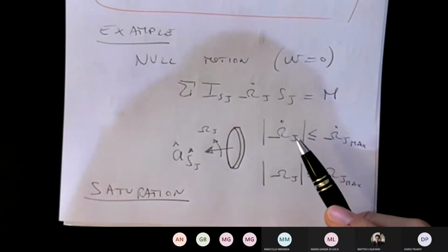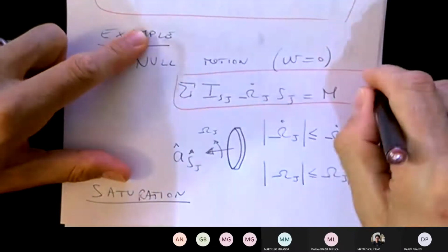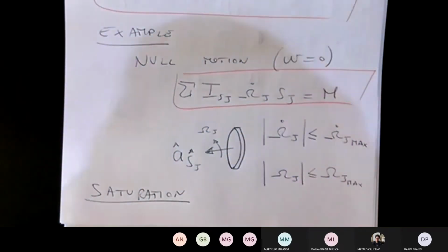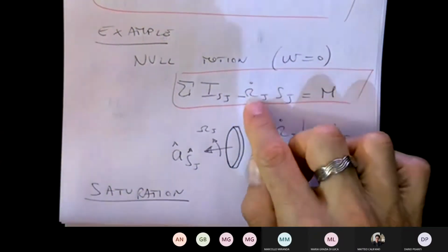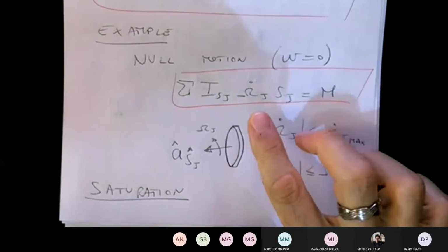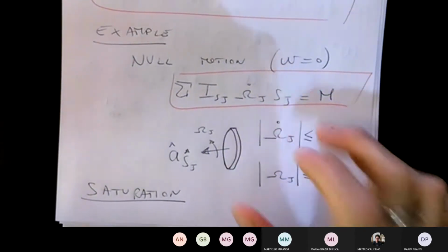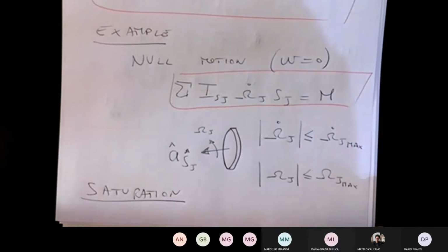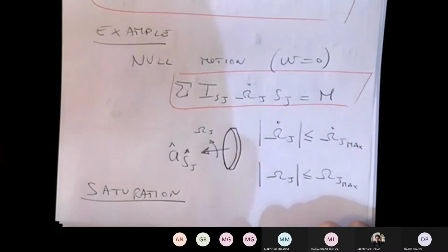So what is usually done is exactly what's described in this equation here. Say that your spacecraft, you don't want to perturb the motion of your spacecraft, maybe it's at zero angular velocity, but you need to slow down the wheel, so you have to actually apply some non-zero omega j dot. Well, what is done is that you desaturate, so you start slowing down, for example, that wheel, but you need to compensate for the torque that it's creating. And so that's done with thrusters or maybe with your magnetic torquers.